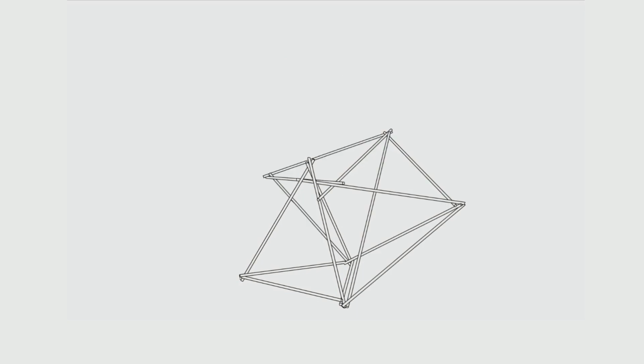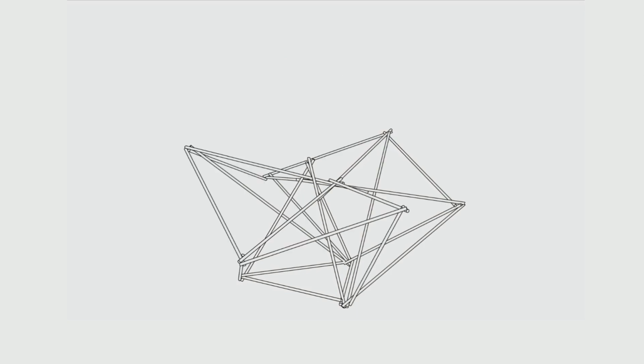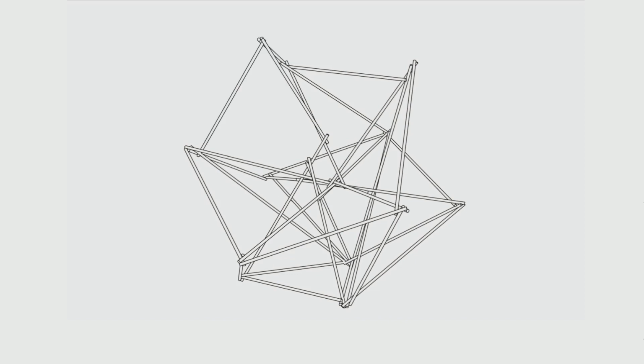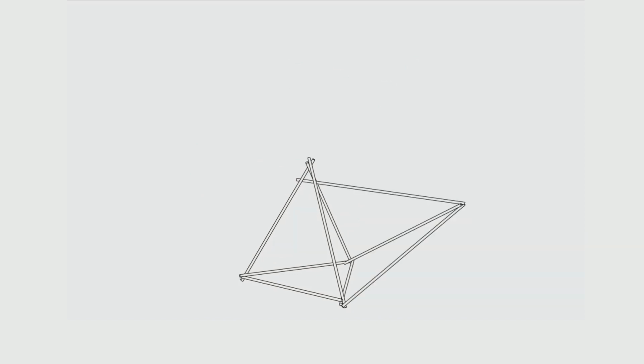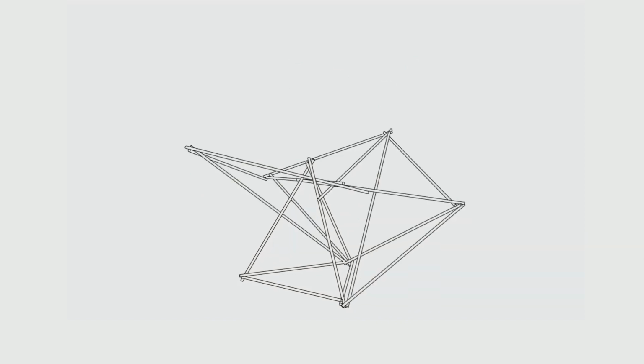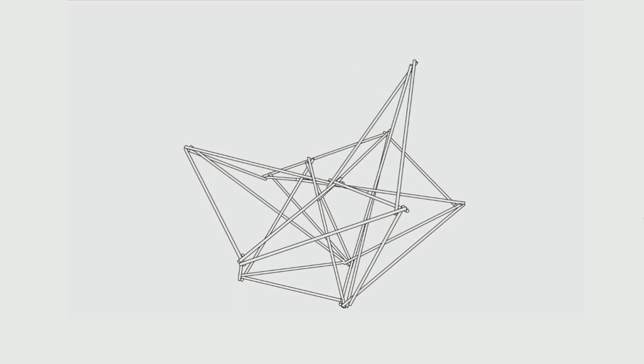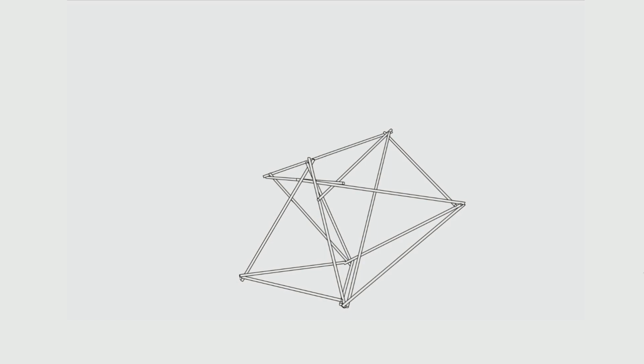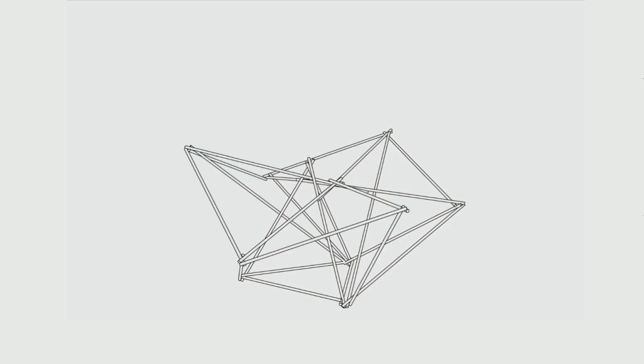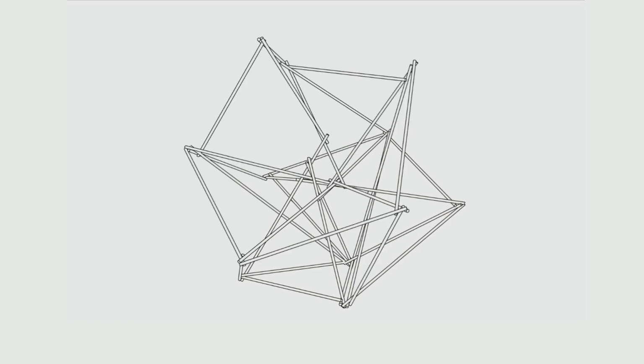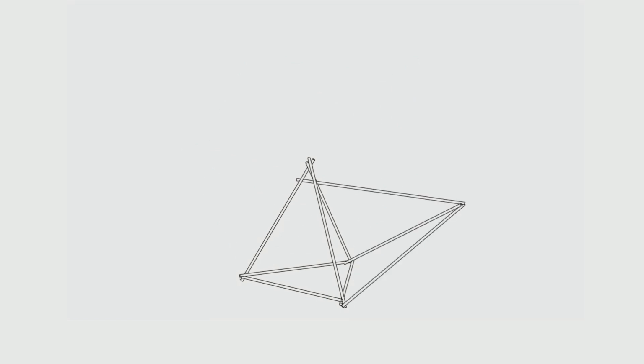Which are sequentially added, and they are allowed to interact. The only goal is to provide a statically determinate geometry. So at every step after placing 3 bars, the structure is again stable. And as I mentioned, everything's based on the sequence. In this case, 1 point and 3 bars are generated at every step of the design process.